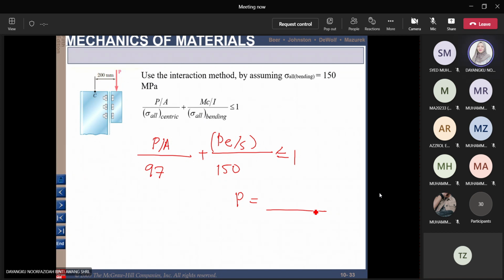So any question regarding the design of the column? Your final will be on design of column. You should be able to determine, first, the LE. Always check for the LE first. Which LE? Whether you need to use 0.5L, or 2L, or 0.7L. First of all, always check for the effective length LE based on the drawing. Check your LE first, then you can continue with calculating the value of your design.